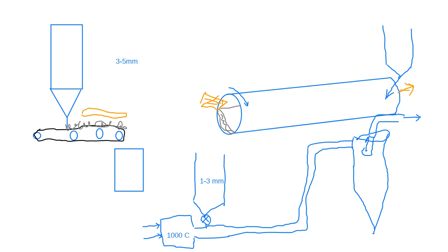Then you've got to design this to be at least 25 meters per second flow, so that you exceed the terminal velocity of the big particles. And so there's another bit of horizontal pipe before it goes into a cyclone. And you have to have a horizontal bit of pipe before the cyclone, because a cyclone has to be mounted in a vertical position as shown.